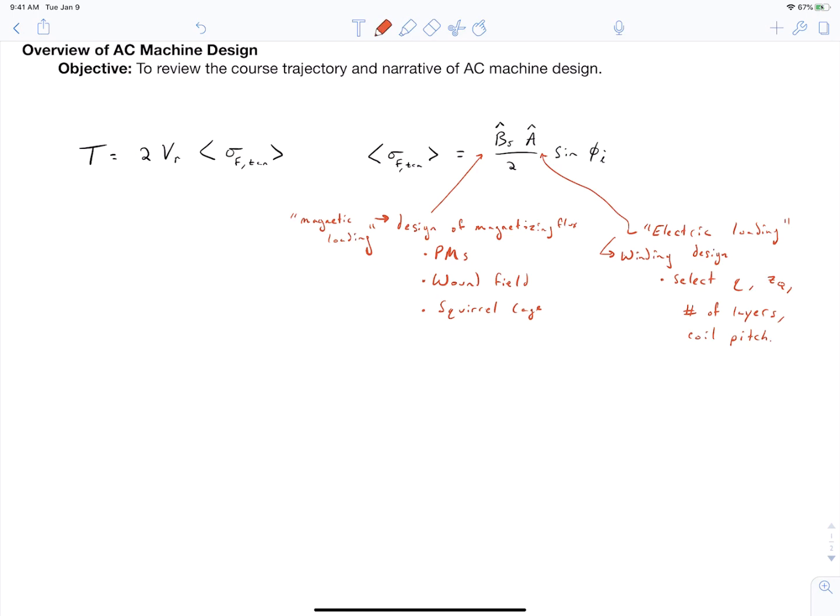What we haven't talked much about is the volume of our rotor. And this is related to the mechanical design of our motor. So there's two key decisions here. The volume of the rotor is pi r squared times L. So it's pi times our radius squared times L, just the volume of that cylinder. And the two decisions are what your radius can be or should be, and what your length of your rotor should be.